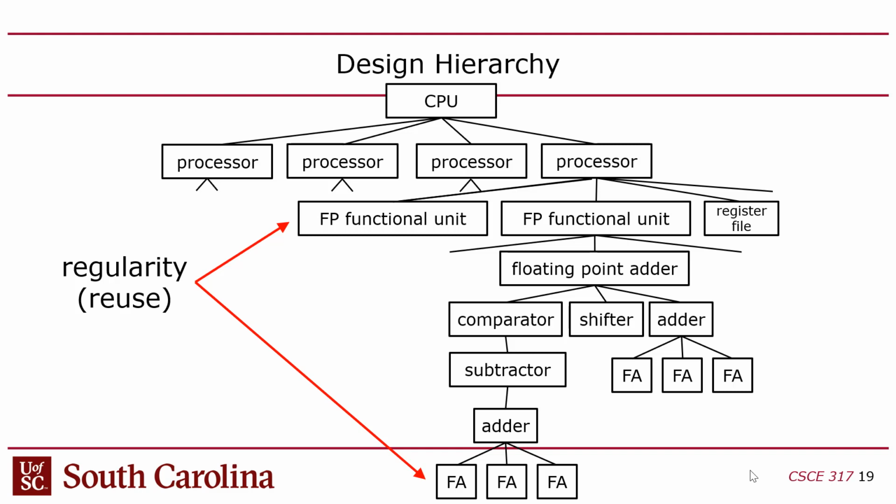That's regularity. And if you can, that's great, because then you end up having very few lines of code written and 1 billion transistors in your chip, right? That's what you want. Because you don't want to have to debug a lot of code, you don't want to have to write a lot of code, but you still want massive chips with 1 billion transistors, right? And so by exploiting regularity, you can get a high degree of reuse out of these modules, and you can create arrays of them like you did in Lab 3, where we created an array of modules for the PWM. I thought that was pretty cool with the generate statement. So you didn't have to write a lot of code, yet you got a lot of logic, relatively, for the amount of code you had to write.